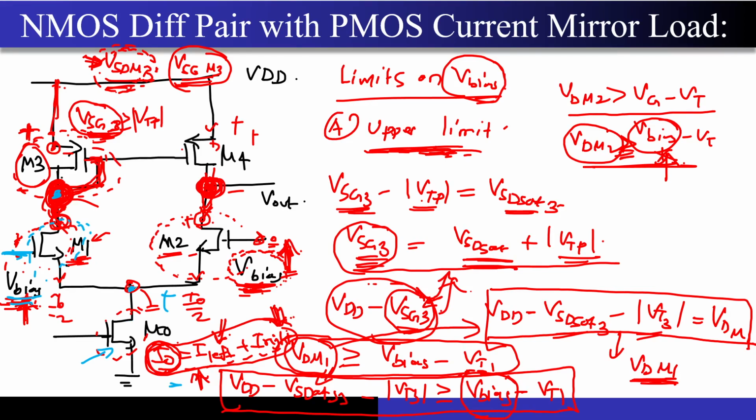No. No, right? Why will it not act as a constant current source? Remember, in the triode case, the MOSFET acts as a voltage dependent resistor. Any change in the voltage that you will see over here, the current that you are seeing over here will not be a constant current source. Even if you are trying to distribute the current, the current value will be changing with the signal swing, and that is a very bad current source, correct? I don't want that to happen, correct? So I have to keep a minimum headroom over here.